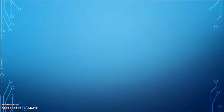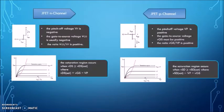Next, as been mentioned earlier, JFETs are divided into P-channel and N-channel. So, here is the comparison between them. N-channel JFET's pinch-off voltage, VP, is negative. Its gate-to-source voltage VGS is also negative. Meanwhile, the P-channel FET's VP and VGS are opposite to the N-channel. Nevertheless, the saturation region of N-channel FET occurs when VDS is greater than or equal to VDS saturation. As for P-channel FET, when VSD is greater than or equal to VSD saturation.